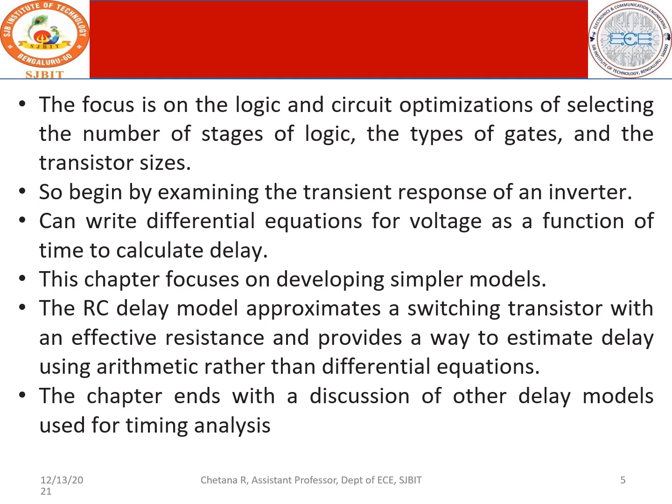This is the requirement, and to understand better we will begin with the transient response of an inverter. Transient response is not just obtained directly; you need to have a differential equation for the voltage, and that in turn will help us to calculate the delay. As I have already told you, the focus is on designing the simple model. Therefore we'll consider the first and simplest model, that is the RC delay model.